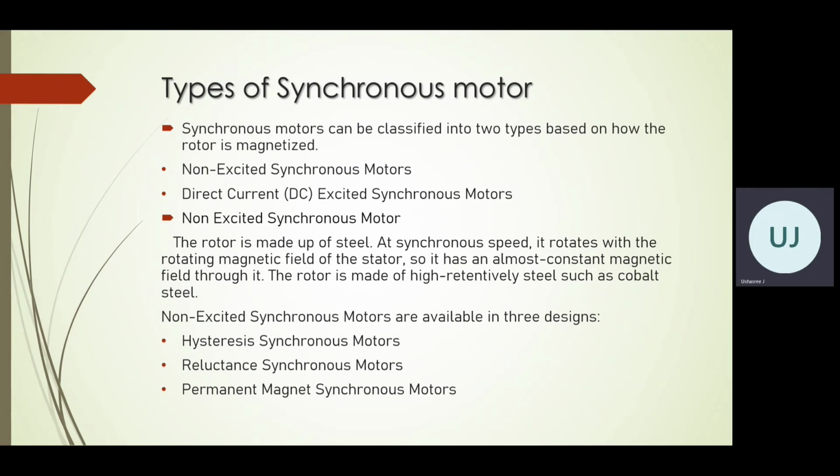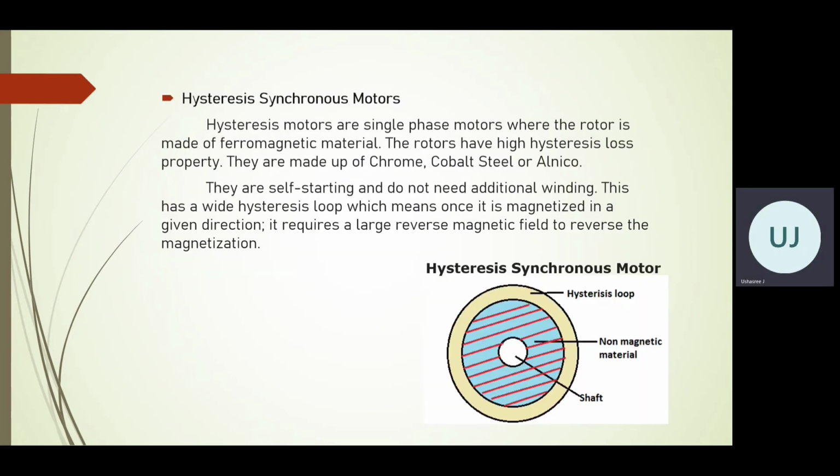Non-excited synchronous motors are available in three designs: hysteresis synchronous motor, reluctance synchronous motor, and permanent magnet synchronous motor. Hysteresis synchronous motors are single phase motors where the rotor is made up of ferromagnetic material. They are self-starting and do not need any additional winding.